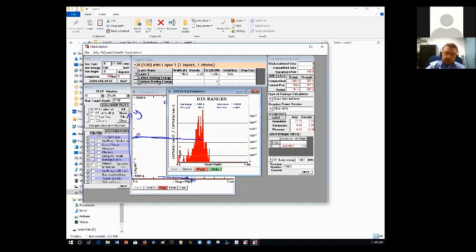I hope this is kind of reminding you of something. With only 100 ions, we were able to observe some sort of a Gaussian distribution up to some extent. And they stopped around here. That's already giving us the straggle too. But see, the complete thing is 1 micrometer, so this should be like 500 nanometers, right? This is more like 300, so that's almost similar to the range here. They stopped around 300 nanometers.